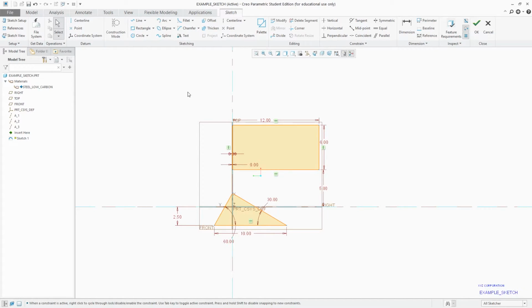If you create this encircle from left to right, then you can see we are creating a selection box with the solid line, which means that only entities which are encircled in this solid square will get selected.